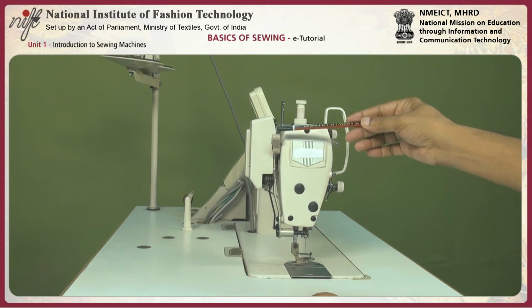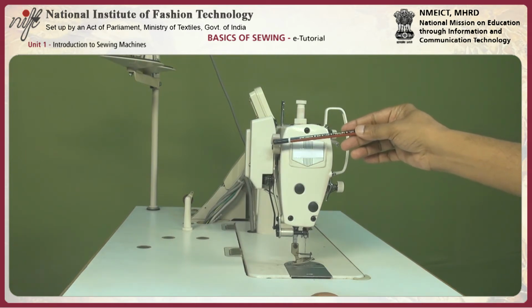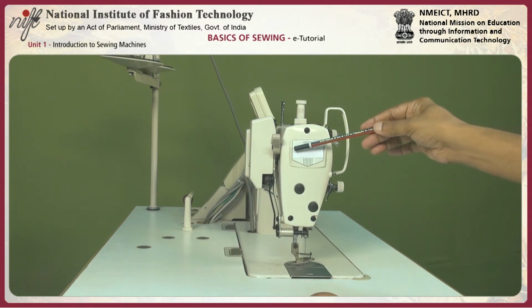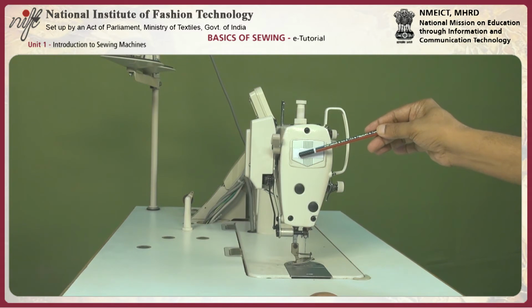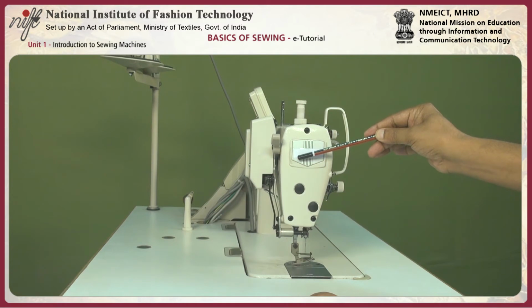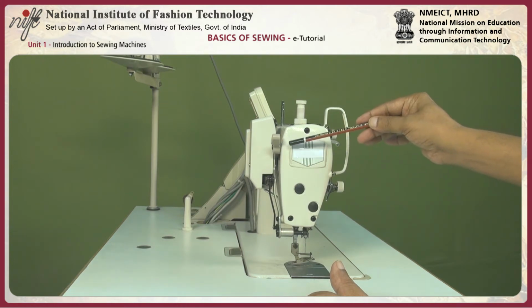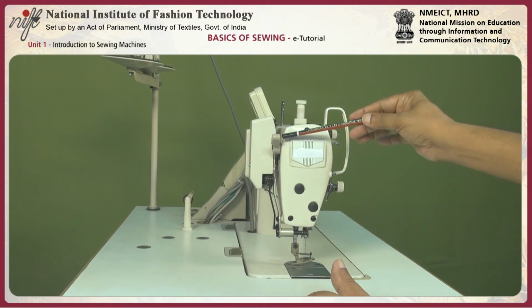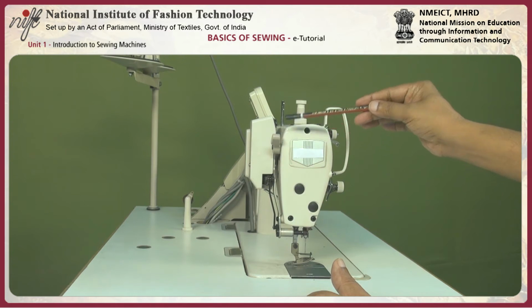In this machine, one is this one. This is lift by hand, and there is a bottom side which you see in black color, which is a knee pressure foot lifter. The purpose of the knee pressure foot lifter is that when the operator is working, he or she can use the knee to lift the pressure foot, so both hands are free. When you are binding a bobbin or you don't want to use the machine, then to continuously keep the pressure foot up, you have to use the hand pressure foot lifter.